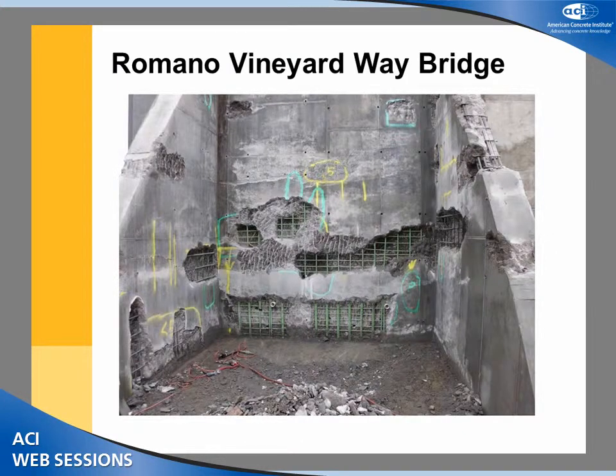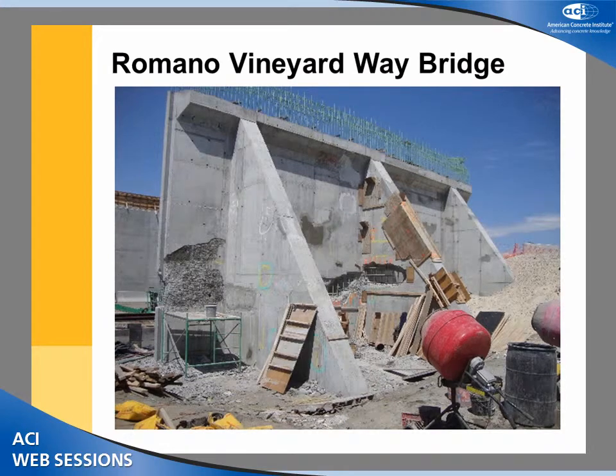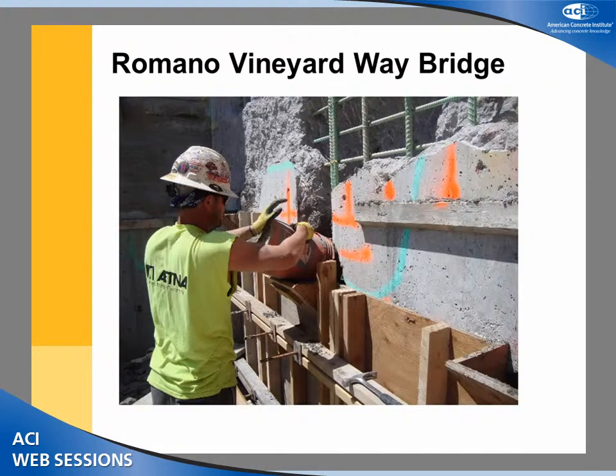This is a brand new structure. So the story doesn't end here. It gets worse, because once you start shipping it out, that's how it looked. So basically, all through the section of the thickness of the repair, this had to be repaired. And really, I'm trying to repair this section with a conventional 7, 8, 9-inch slump. It is a challenge. So the prepackaged SCC, again, helped out quite a bit in trying to get these repairs done. And you can take a look at this.